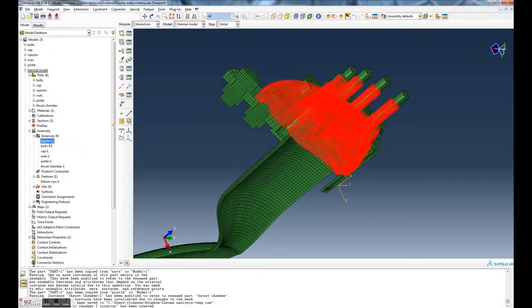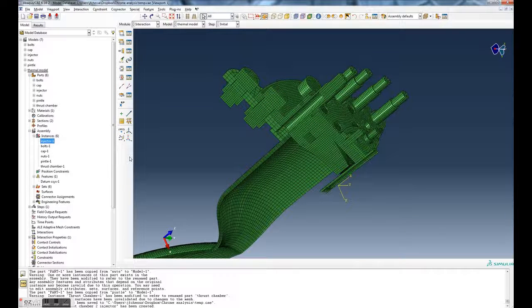And now we have the displacement, so there it is, okay? So you can see the displacement of node 2 and node 3, right? Now, this is just printing out the displacements, so no big deal there. This just loops over each node and computes and writes out the X and Y displacements. Reaction forces, in the way we've always done it, multiply the stiffness matrix by the solution, and you get the external forces.